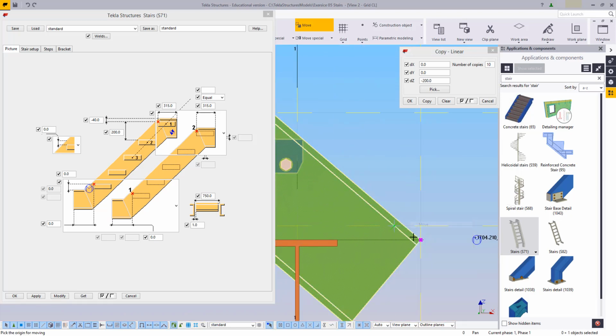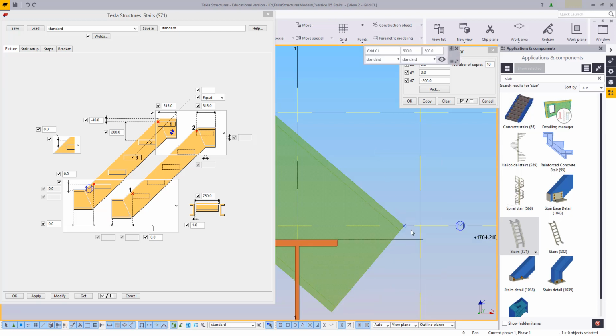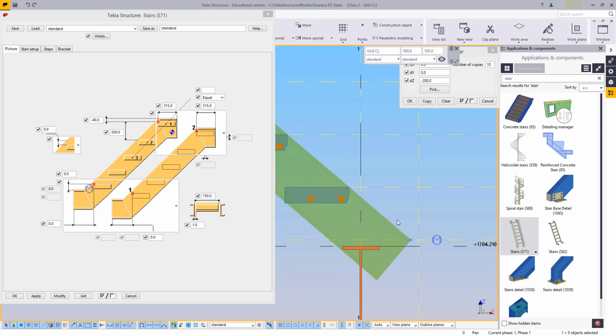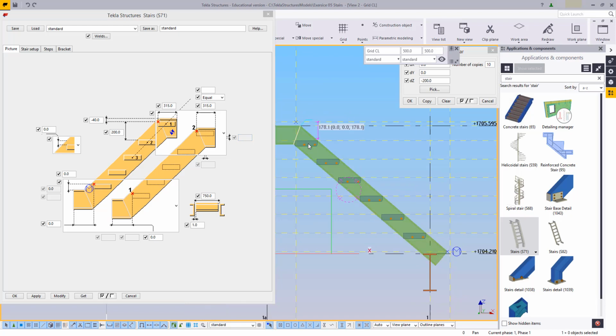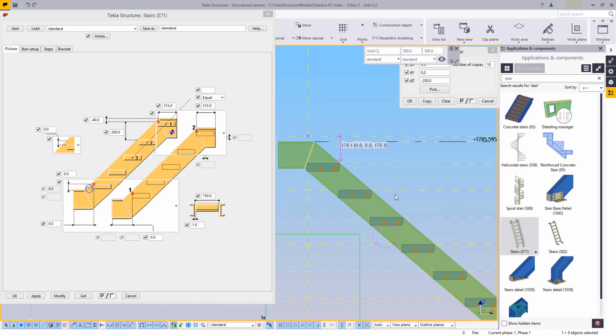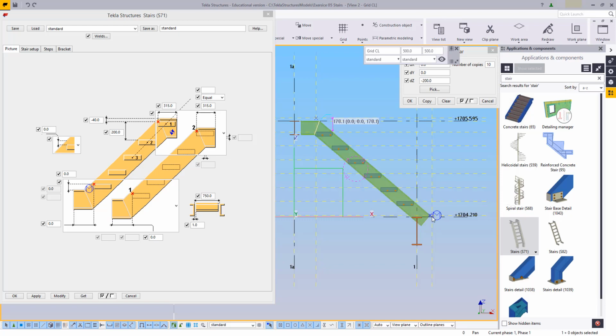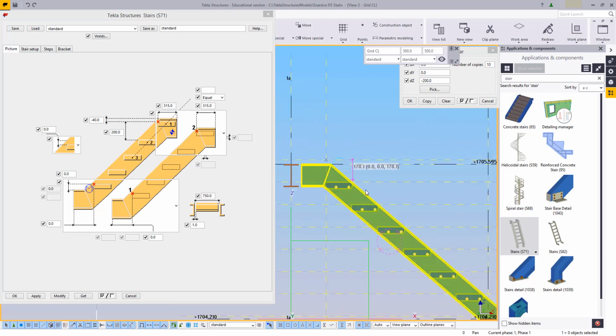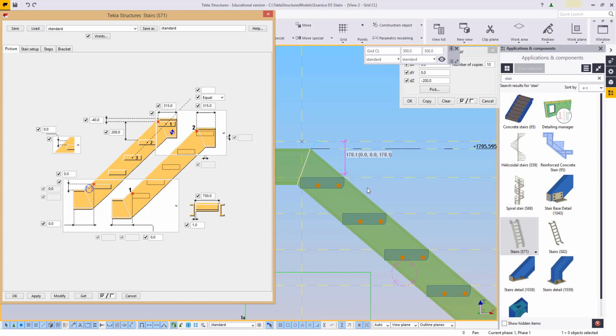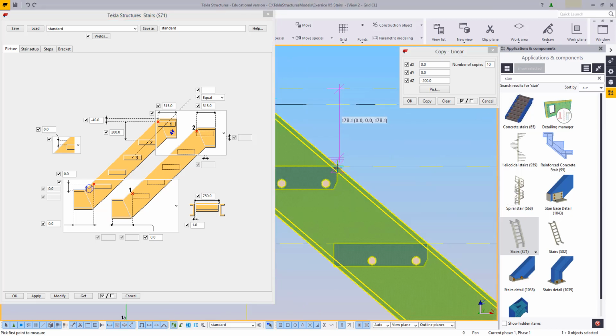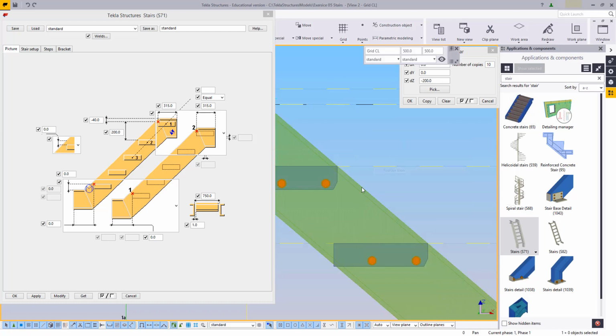After that, I'm going to move my SFP point slightly up to about here. It's still in its original line, so it hasn't really shifted or risen, but because it's now equally divided amongst 200, I'm getting the correct amount for my stairs. Just confirm that with a dimension. It's 200 and 200. Good.